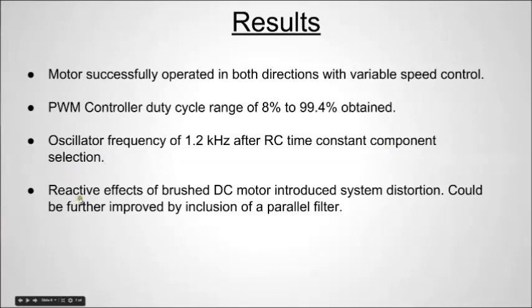Also, an observation I made was that there were some reactive effects introduced into the system that create noise and distortion, most likely from the inductive nature of the DC motor windings. This could probably be mitigated by including a parallel filter across the lead terminals of the motor.